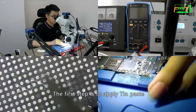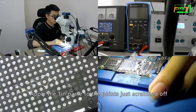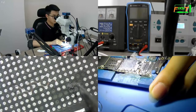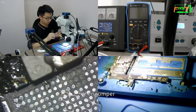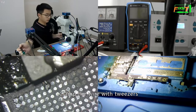The first step is to apply thin paste. Apply the thin paste to the points just scratched off. Then jumper. Clamp the wire with tweezers.